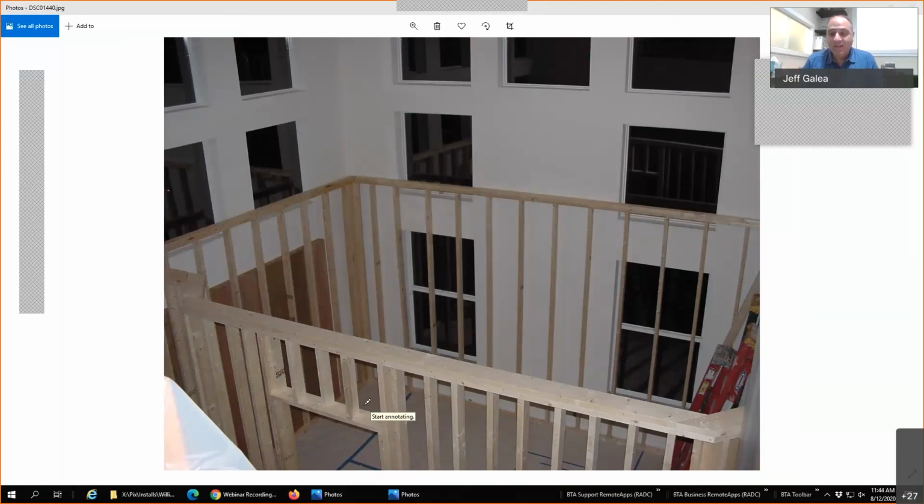Something might resonate, and it's typically air conditioning vents. So I would recommend linear diffusers for that. You're better off having more linear diffusers so that there's no whooshing sound when it turns on and off. And also think about the heat load in that room, that you'll have a bunch of bodies in there at the same time.